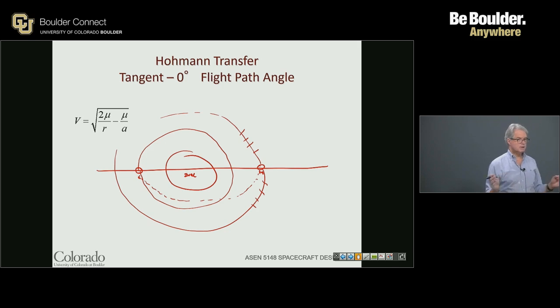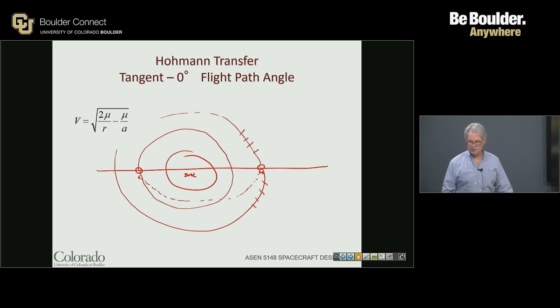And Mars is one of those planets that has an interesting period. Every year it's sort of next to us, and the next year it's away from us, next to us. So the launch window out to Mars, what we call a synodic period, is one of the most difficult to get to because it's in resonance with the Earth orbit. If we go further out to the outer planets, we can go almost every year because they tend to look like they're on the other side of the sun. To the inner planets, more time and thought has to go to it, but Mars is about the most difficult planet to get to. What we would like is for everything to line up like this so we'd have the ability to do a Hohmann transfer.